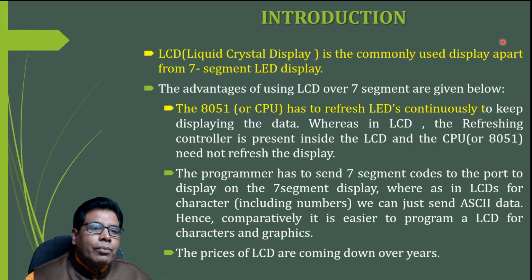Firstly, the CPU or 8051 has to refresh LEDs continuously to keep displaying the data. So when we are using the multiplexed mode of the 7 segment display, at that time the refreshing of LEDs has to be done continuously by the processor or the CPU.